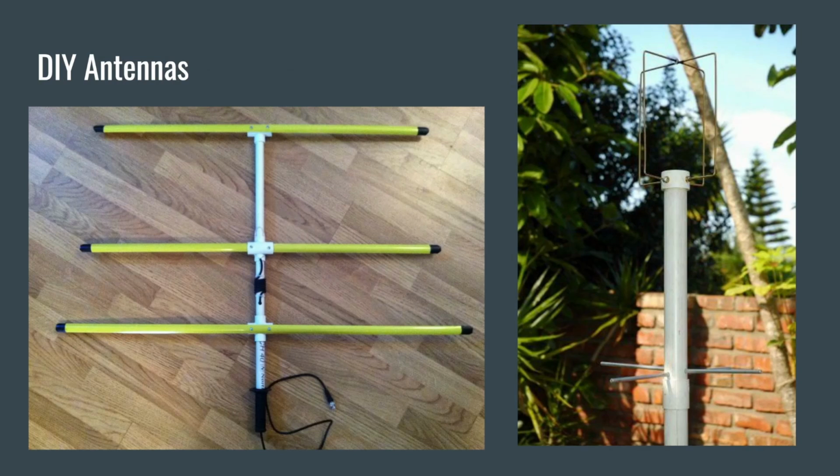For the most part, you have the option of two different antennas. Either a directional antenna, which requires it to be pointed to where our satellite is, or an omnidirectional antenna which does not get pointed but can receive signals from all sides. The difference between the two is that the omnidirectional antenna needs a much stronger signal, where the directional antenna can be pointed to a lower power transmission. Both of these antennas can be made easily at home with bits and bobs from a hardware store. For example, this directional antenna was made with an old tape measure.